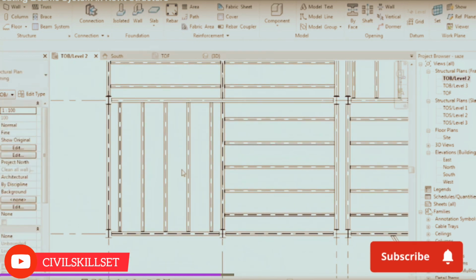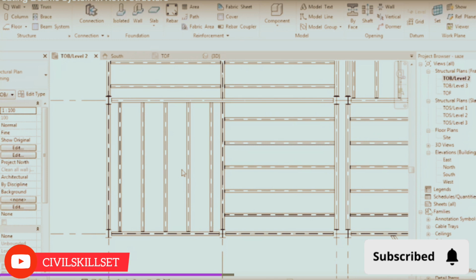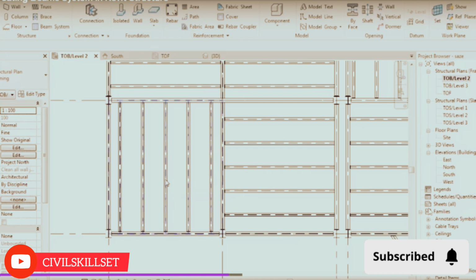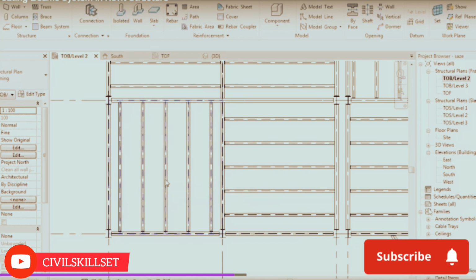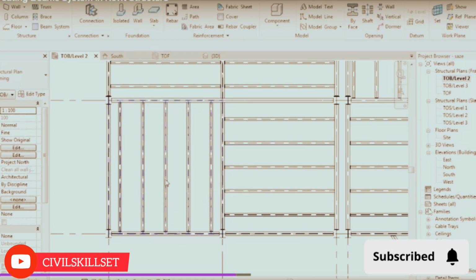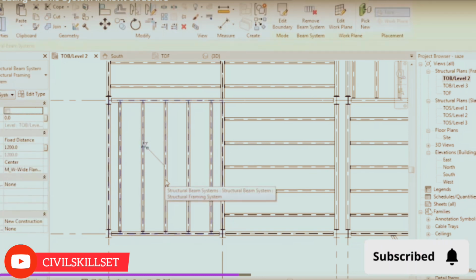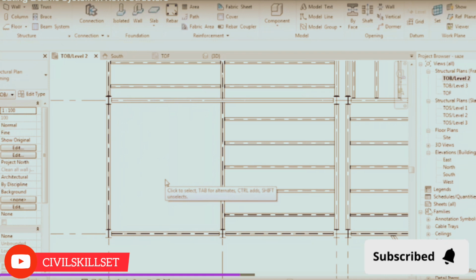Let's delete this system here. When you want to select the system, either to delete it or edit it, when you come here, one of the parts of the beam is selected. Now, you see, this is the beam system. The previous time, the beam system wasn't selected, right? Now, this is the same thing. When you see that dashed line, all of the system is selected.